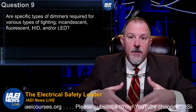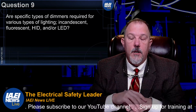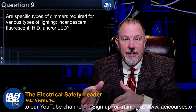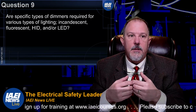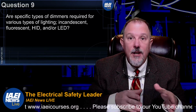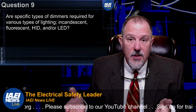We know there are requirements around that. We've also talked about compact fluorescent and fluorescent lighting, its current signature and current draw. And we know I need a special breaker if I'm going to use that circuit breaker as a switch to turn fluorescent lighting solutions on and off.